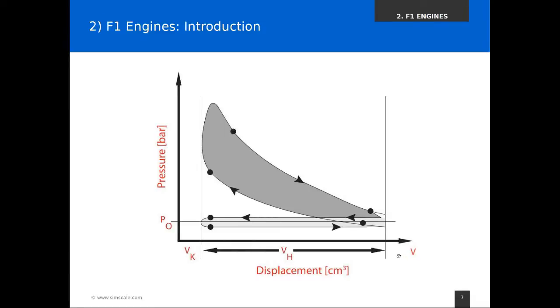So let's start with this compression stroke. When we started, we have our entire gas or combustion chamber filled with a mixture of fuel and air. So what we do then is both valves close and the piston moves upward and really squeezes it and compresses it to a very small volume. So the volume decreases, and as we decrease the volume, we increase the pressure. So we travel along this curve here in this direction indicated by the arrow. I hope you still remember the strokes.